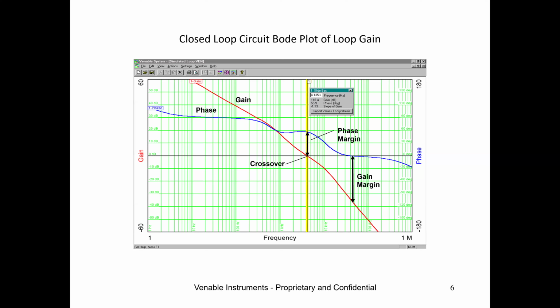The way I was taught in school is you measure phase margin from a 180-degree point if you're trying to determine stability, but that doesn't take into account the inverting 180 degrees phase shift, inversion of negative feedback. So usually when they're talking about that, they're talking about the final 180 degrees of phase shift and not the entire loop. But ours measures the entire loop.